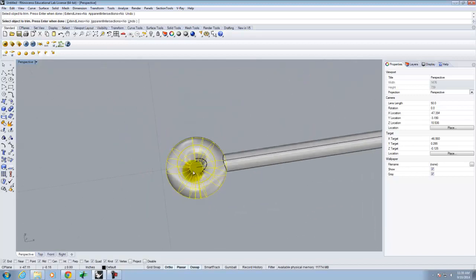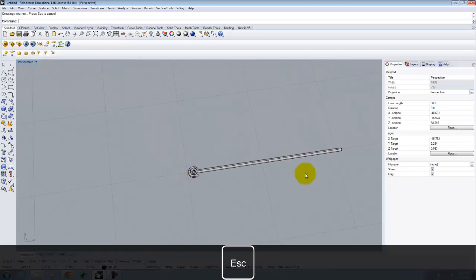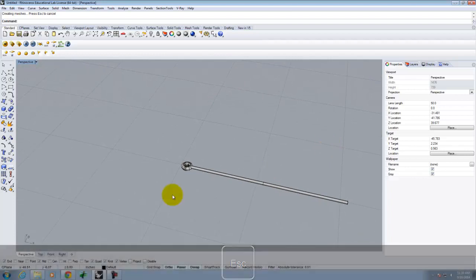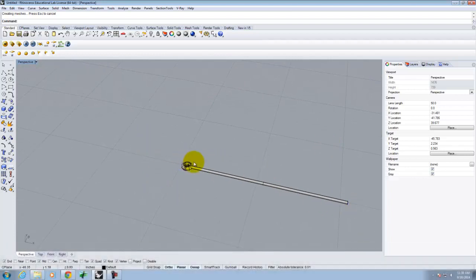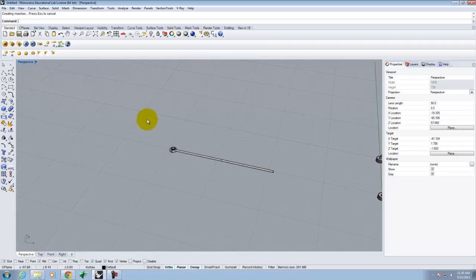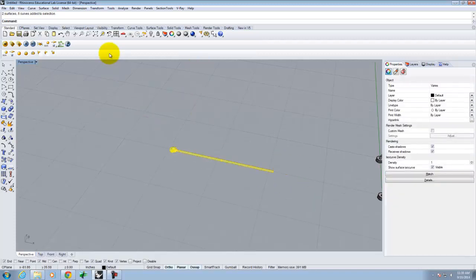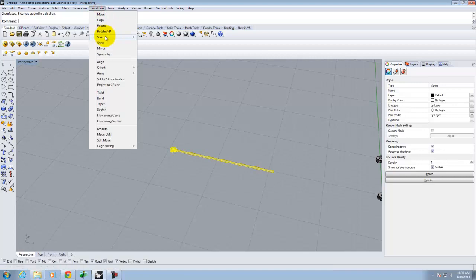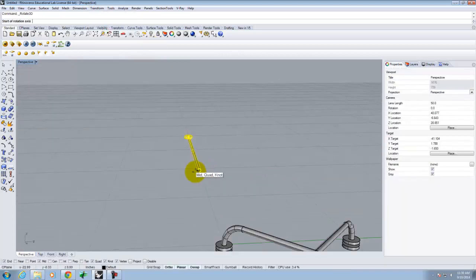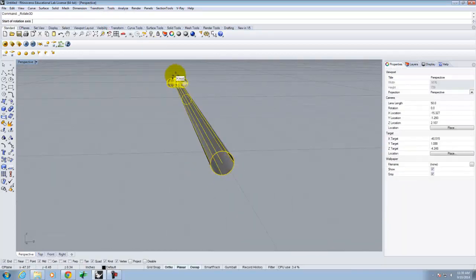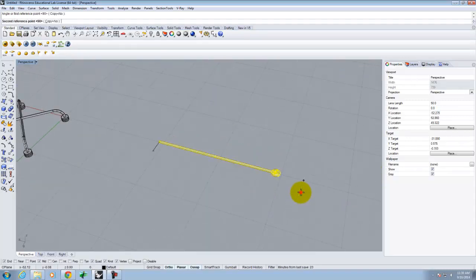Okay, that looks pretty good. And so now I have this as 2 feet long, right to the center, which is what it needs to be, and that's from the glass surface. So let me take this whole object and rotate 3D, transform, rotate 3D, and stand it up. I've left the curve that's in the center because it'll help me manipulate the object. That's going to be my rotation axis, and I'm going to fold it up that direction.